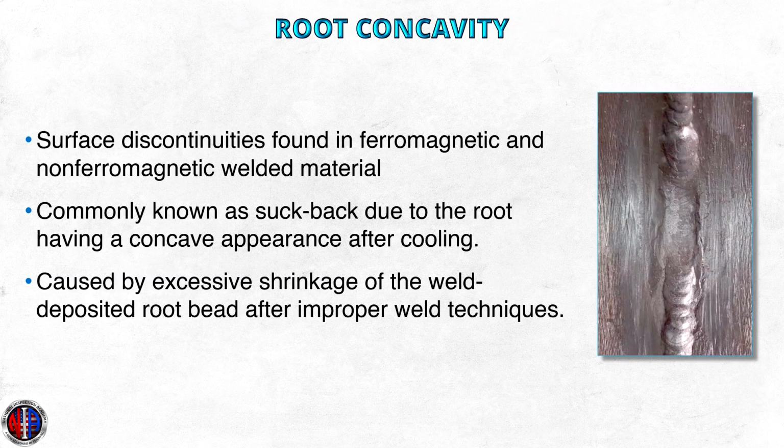Root concavity. A concave root surface comprises surface discontinuities found in both ferromagnetic and non-ferromagnetic welded material, commonly known as suckback due to the root having a concave appearance after cooling. The discontinuity is caused by excessive shrinkage of the weld-deposited root bead after improper welding techniques.